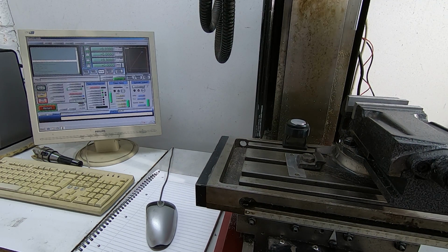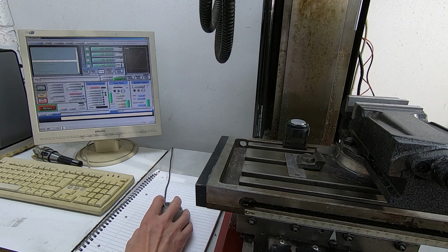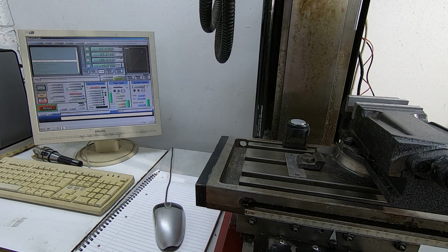So now it's done that, it's zeroed, and that's the G53 fixture that's zeroed. So notice that the G54, which is the one that we're now looking at, is not zero. Now what I'm going to do, just as part of a test, is we're going to zero on the top of that plate, just because I want to demonstrate how the macro works.